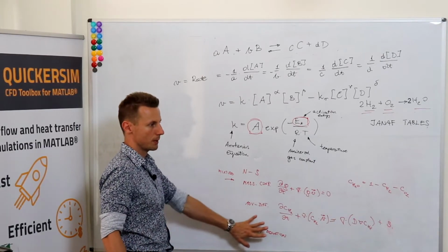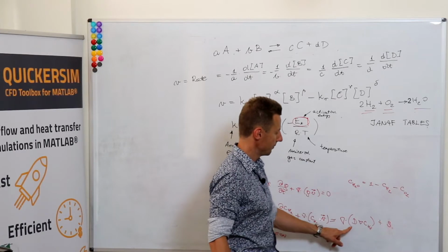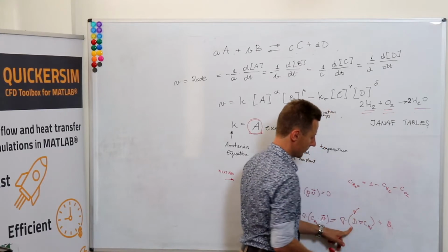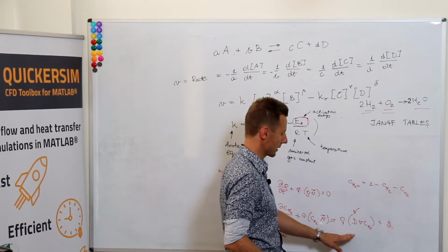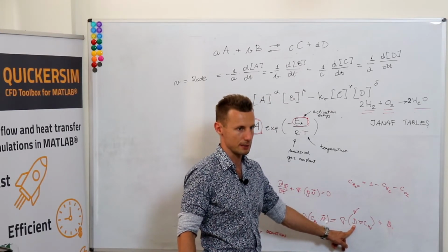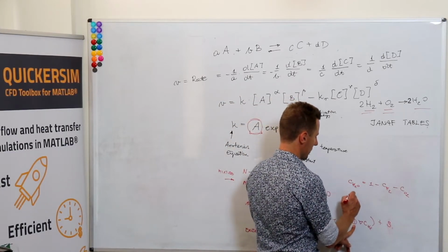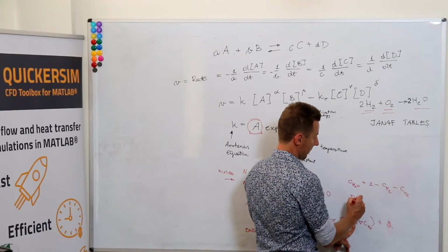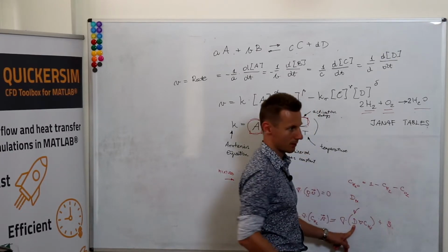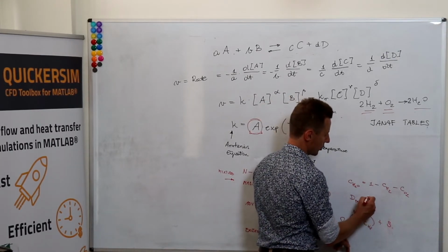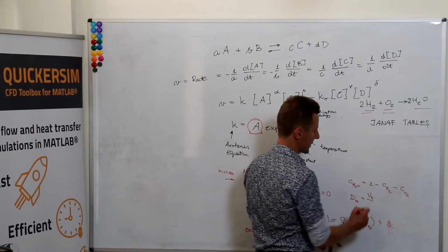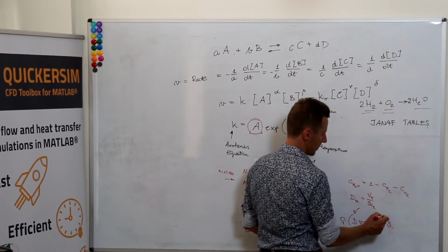The energy equation needs to be added to the system, certainly. If you're dealing with turbulence modeling, then this one, the Schmidt number, exactly. If we say that this is the physical mass diffusivity, then this one needs to be changed by D, the physical mass diffusivity, plus, in general, turbulent viscosity divided by the turbulent Schmidt number.